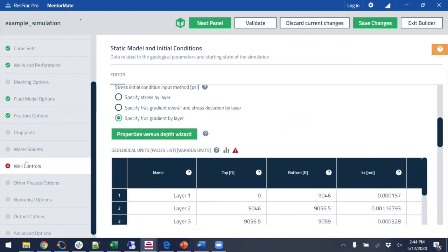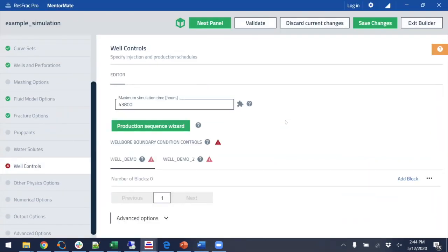I'll make a comment that I noticed today or yesterday. Again, I'll reiterate the point that if you change the boundary conditions all the time, it slows down the simulation a lot. So personally, when I'm doing this, I'll change it maybe once a month. If I eyeball the bottom hole pressure versus time and it looks like it was about constant for 3 years, I'll just use one bottom hole pressure for 3 years. Don't feel like you need to change things every day or every week. You're just putting in a lot of detail that's not really going to have a big impact.